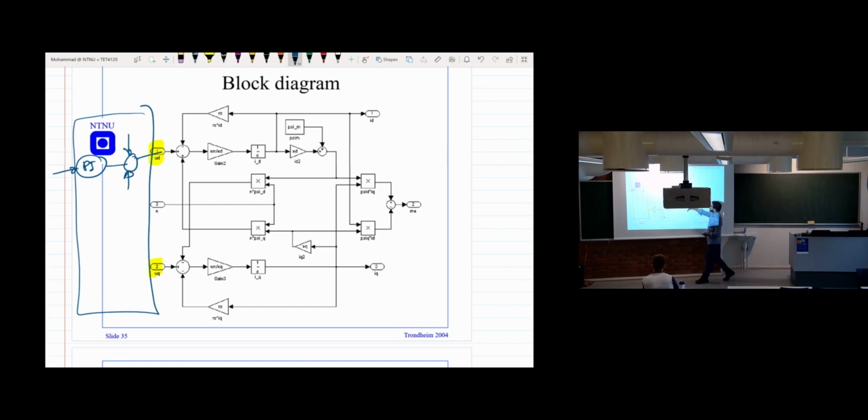So you have the dynamic model, and based on that, we will implement the control. And we see it has some feed-forward terms and some cross-coupling terms. So we try to cancel the cross-coupling term. Since you can see we are adding this plus here, we will put something minus the same component here. Then it can cancel. That's what we did to neglect the effect of the cross-coupling term.